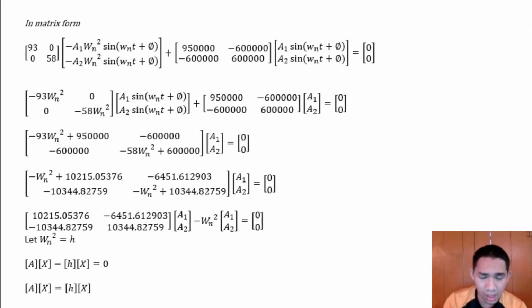We have four separate iteration equations that we are using. Each of them is used to find the highest natural frequency and the lowest natural frequency, for both the stiffness coefficient of K neoprene and K sorbothane. After we get the values, we do the validation.